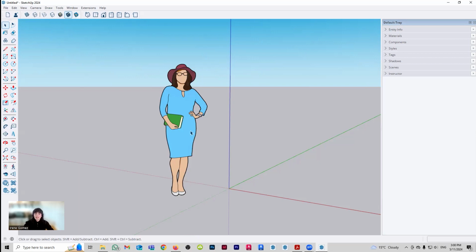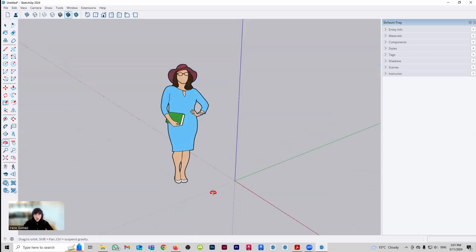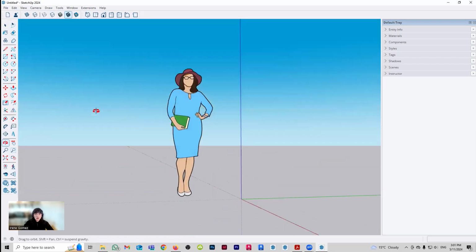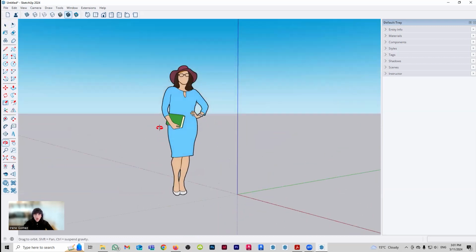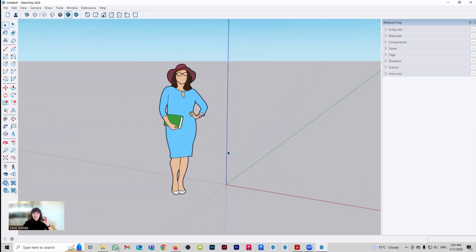And then finally, because this is not AutoCAD 2D, this is a 3D program, we have Orbit. So Orbit is accessible by pressing the wheel, and you can see that little twirl, little arrow. So what's going to happen now is that when you move your cursor, that is going to allow you to orbit around your model. And this is a very important thing to understand. In SketchUp, the camera is moving, not the object. It's not like you're holding an object in your hand and you're rotating it. No, no, no. You are moving around that object.